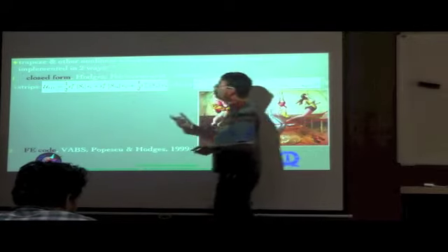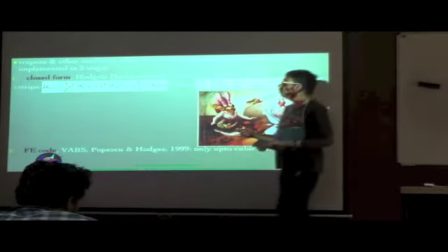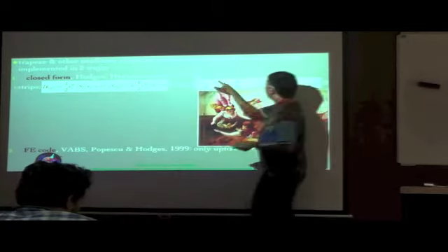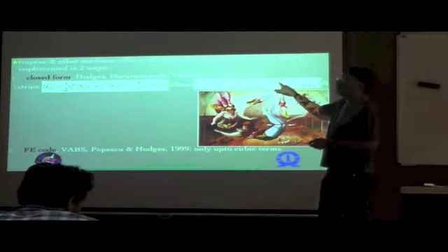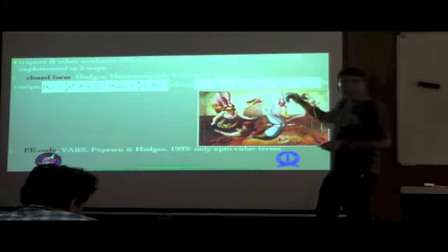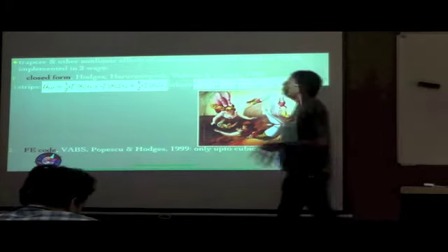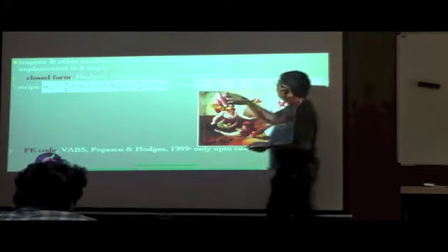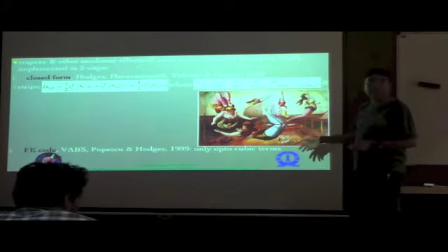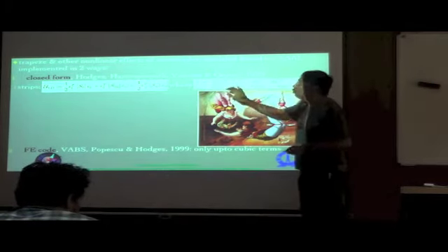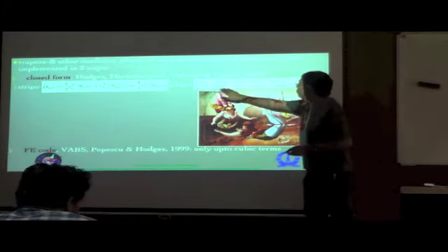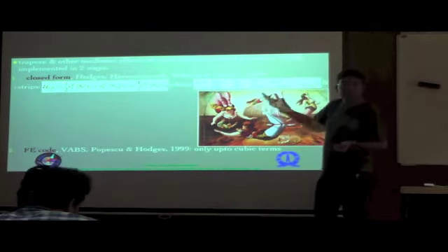But what makes it nonlinear are these two additional terms, where again the same symbol epsilon L is used for this column vector of 4 one-dimensional strains. Remember that all of these are one-dimensional strains in the sense that they are all functions of x1 alone. And then you have epsilon n, which consists of not the entire set of the quadratic components, but basically a few which are asymptotically relevant. Kappa 1 squared, kappa 2 squared, for example; kappa 3 squared is not there.